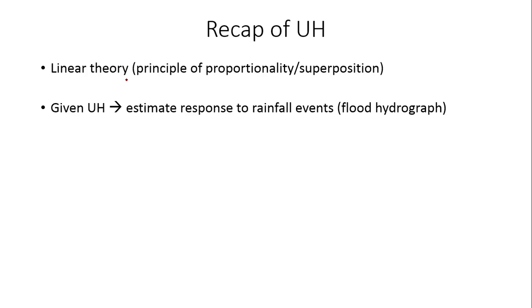This particular catchment received 3 centimeters of rainfall in the first 4 hours and 4 centimeters in the next 4 hours. What will be the flood hydrograph? Something like that would have been asked, right? In this you can have so many variations of this. I can either give you the actual rainfall and the phi index and ask you to find out the effective rainfall, or I can directly give you the effective rainfall and ask you to find out the flood hydrograph, right?